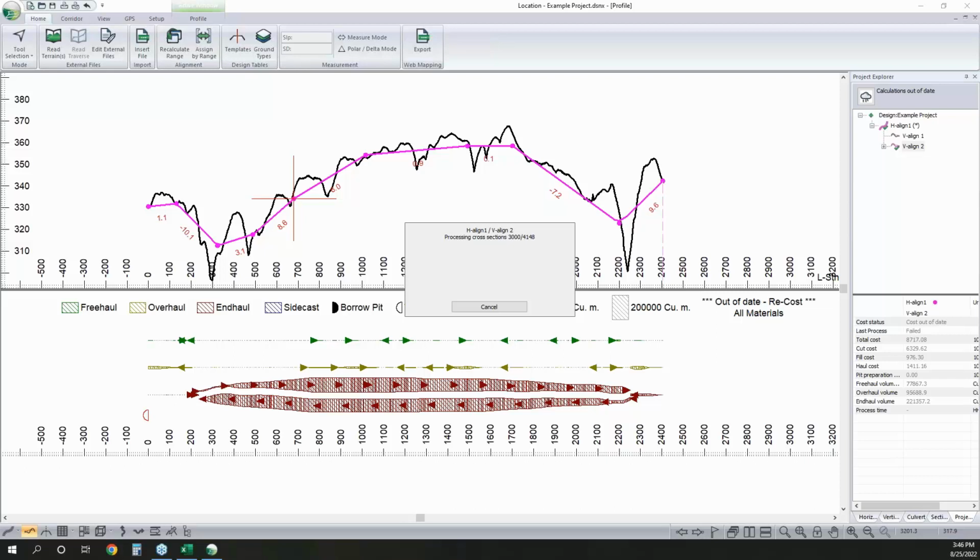either relied entirely on photo interpolation and interpolating the ground types based off the topo data, and I said, well, this is probably shallow soil and solid rock there, maybe based off of bedrock mapping or something like that. And I've tabularly assigned the ranges where my material changes and the depth changes for that material. So I've done that in the assign by range.